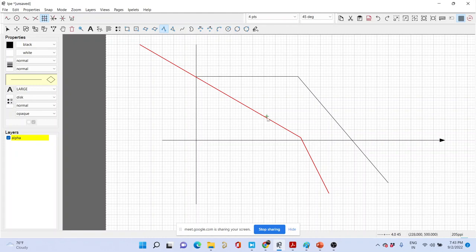So what is preferable is, instead of using a simple PI controller, we place a 0 over here. At DC you are going to have a high gain, but over here, as you are placing a 0, the pole gets cancelled out.